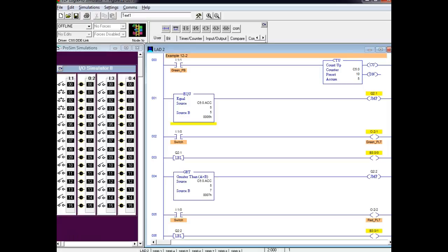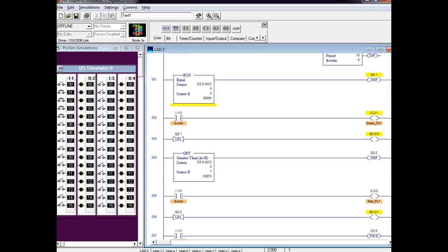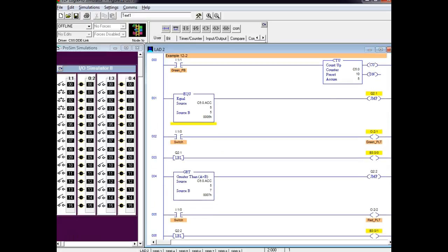You push the button, and it goes to the force. But you've got to be real careful, especially forcing inputs and forcing outputs, because you can get somebody hurt or killed. A relay has a button that you press to force a relay.